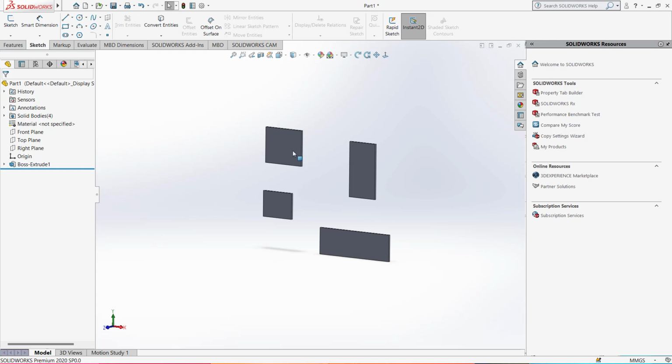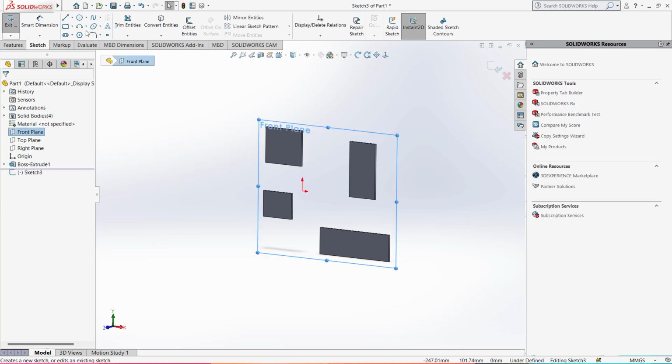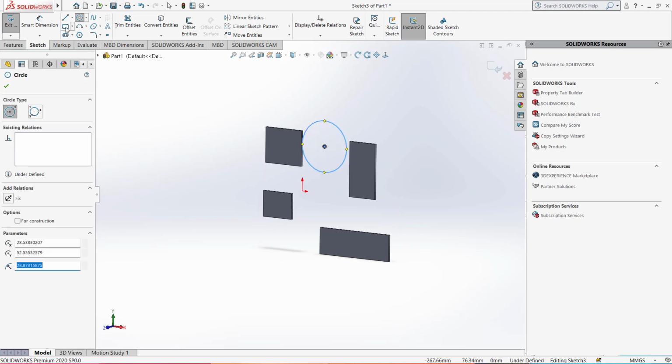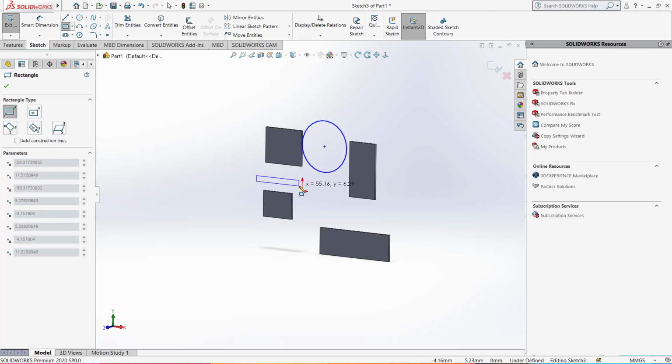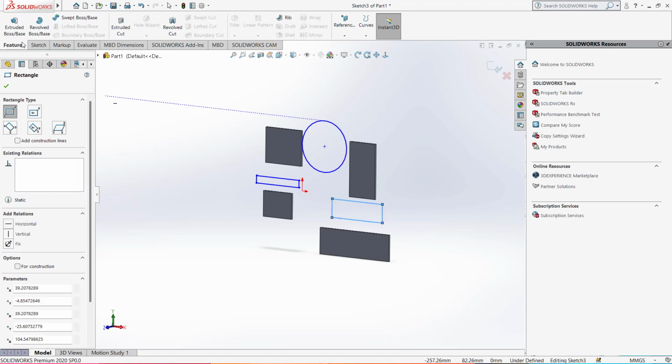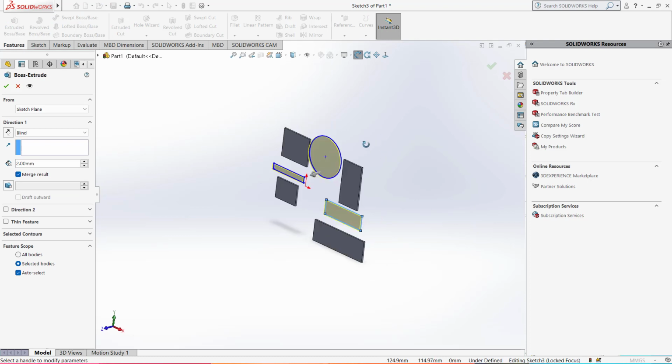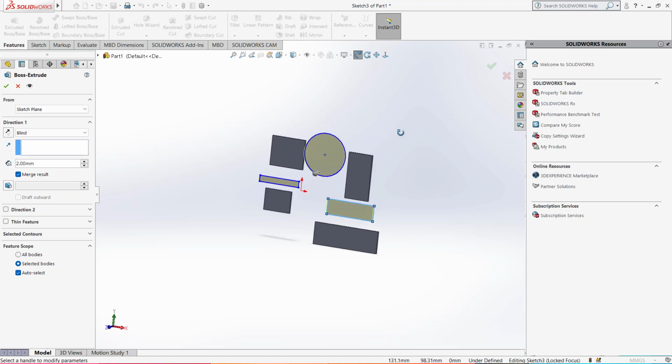All right. So being able to identify the plane in which you're working works hand in hand with the sketch tool. All right. So assuming we're trying to create something in the middle here, still on the front plane, then we would have to hit the front plane and hit sketch. Then we can go ahead and put that thing in the middle there. So like you can see, we have our designs in the middle now.